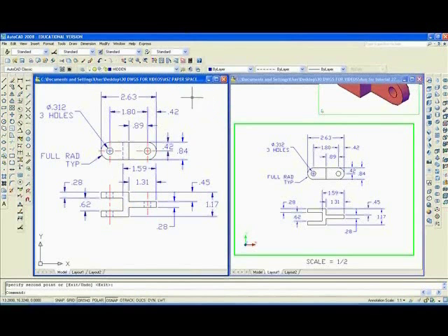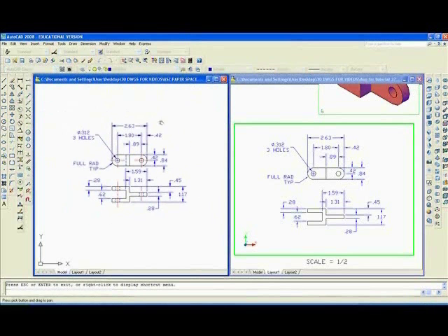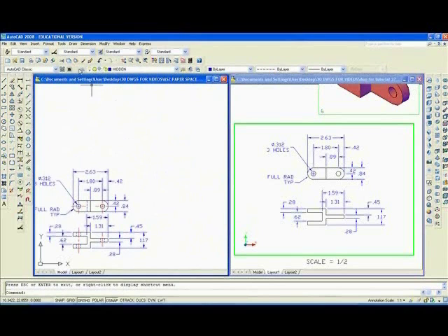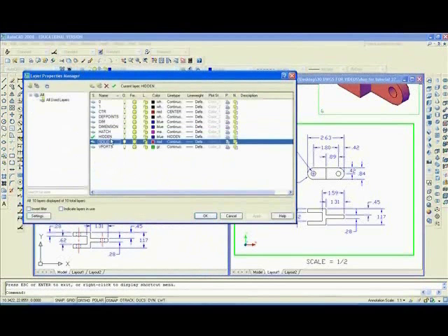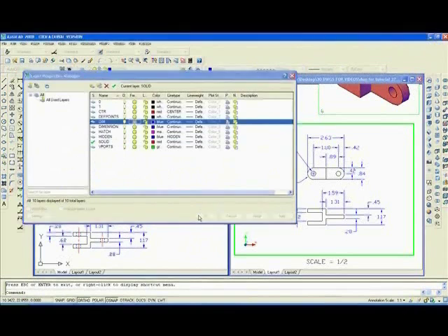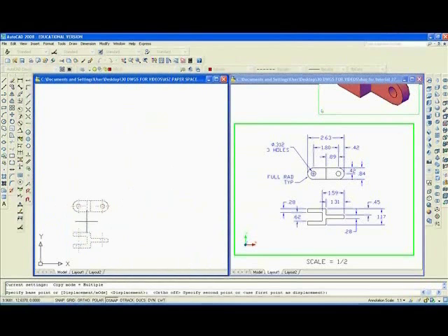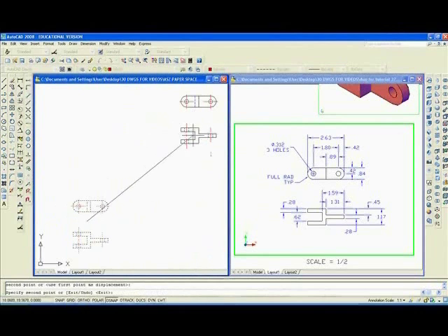And so what I'm going to do is, as usual, shrink down the drawing, pan, put it over to the lower left, probably go to layer solid, make it current, and freeze the dimension layer. Then I'll want to copy the object with ortho off and move it to the upper right as a basis for making the solid model. And then I'm going to thaw the dimension layer.